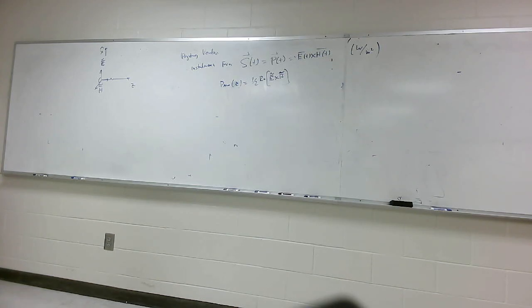That electromagnetic field can vary with time if I put a time-varying voltage on, but it's not propagating. Nothing is launched. If I just have a capacitor and I charge it to a voltage, there's an electric field out there, but no energy is being lost. All the energy I put into that capacitor I can get out. Do you all follow me on this? The stored energy is 1/2 CV squared. If I shorted a resistor across that, all that energy would be dissipated in that resistor as heat. With me? Typically it's heat.